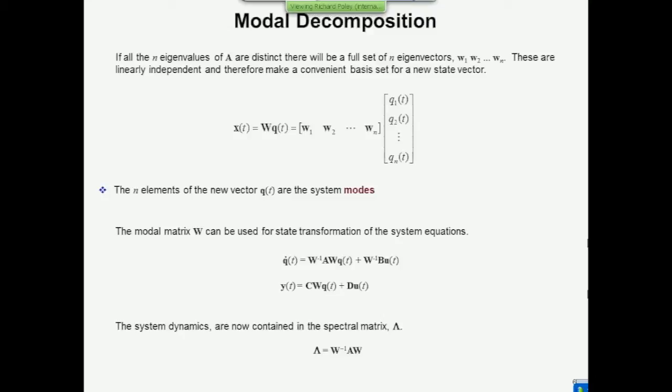So yeah, this is what it is. Now, there's another notational change I want to make you aware of. So this is the new state equation, and this is the new output equation. And because of this unique choice of columns for the transformation matrix W, we end up with a diagonalized new system matrix, uppercase lambda, and lambda will contain along its leading diagonal the eigenvalues of A.